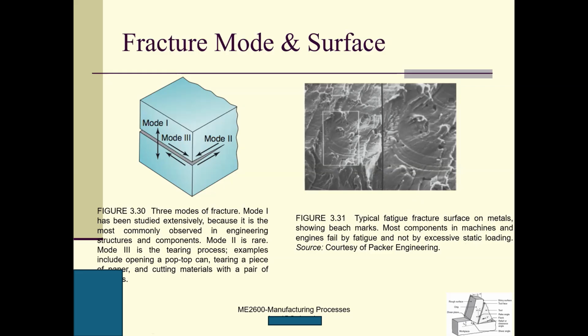Fatigue means that you apply the load cyclically, repeatedly. So for example, if I have a beam, maybe suppose this is a shaft or beam, I bend it this way, and this way, and this way. As time goes, even though the bending stress resulting from this bending moment is very, very low compared with the strength of the material, after many cycles the specimen still fails, and this is called fatigue.